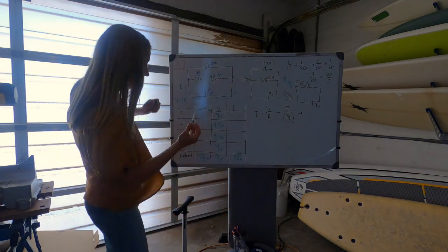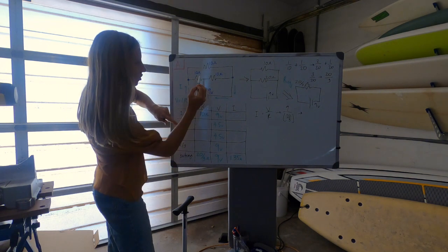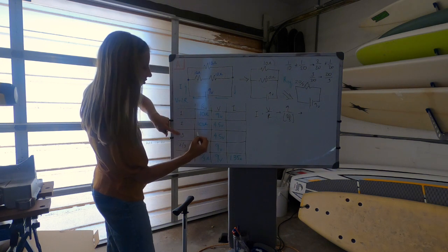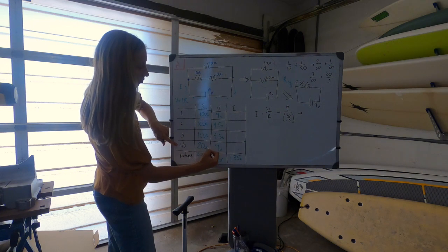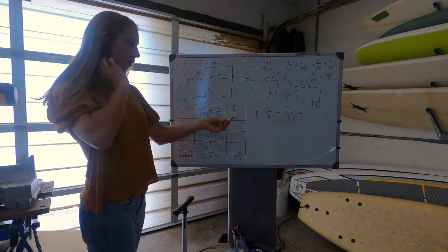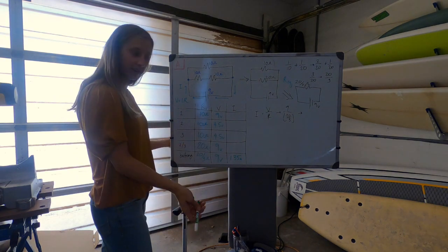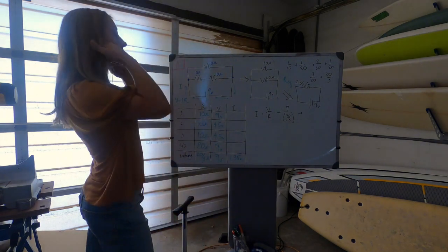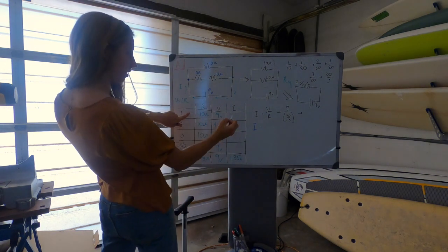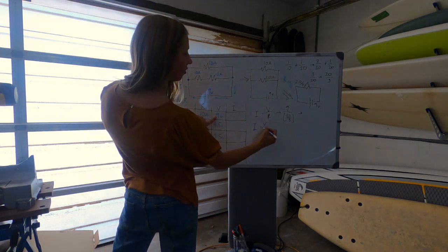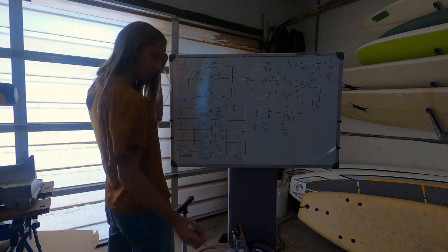Okay, let's see. We also know all of these resistance values. Resistor 1 is 10 ohms. Resistor 2 is 10 ohms. Resistor 3 is 10 ohms. What's 2 and 3 combined? 20 ohms. Oh, and now look. If we know any 2 things in a row, we can find the third. So from here, it's just this over and over again. So, okay, let's do this one. What's the voltage? It's 9, and this is V over R. So we're doing 9 over 10. So 0.9.